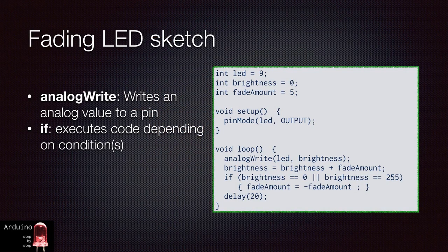Here is a new sketch, slightly modified from the sample in the Arduino IDE, which you can load by going to File, Examples, 01 Basics, Fade.